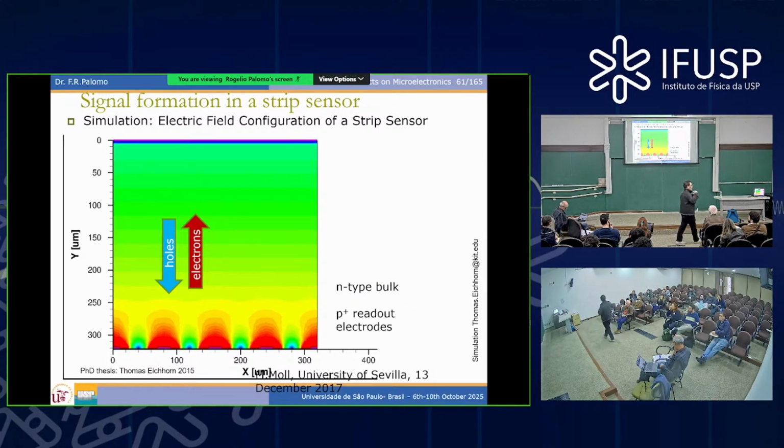That degradation will manifest in reality in several ways. Okay, those are the symptoms. But the reality is that you are destroying the electric field, the homogeneity of the electric field. It was in those years an N-type bulk. Nowadays it's a P-type bulk because we were testing precisely which were better, an N-type or a P-type bulk, N in P or P in N, for the high lumi, in those years it was LHC.